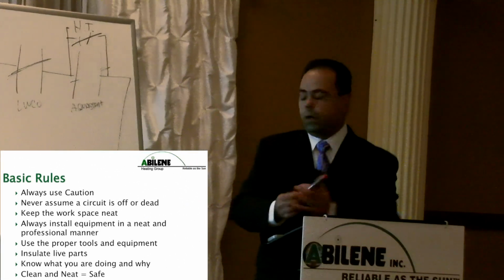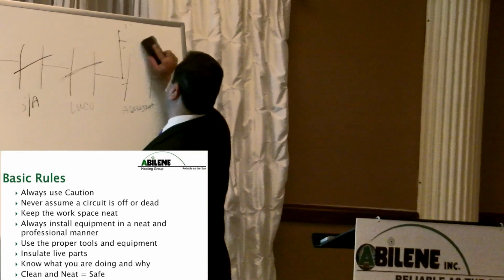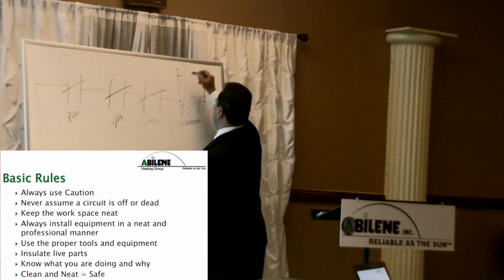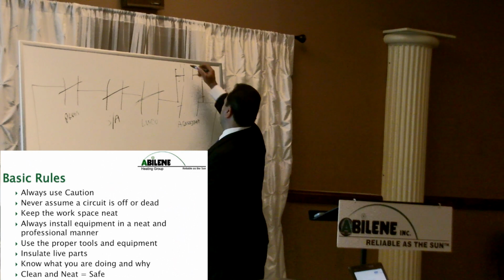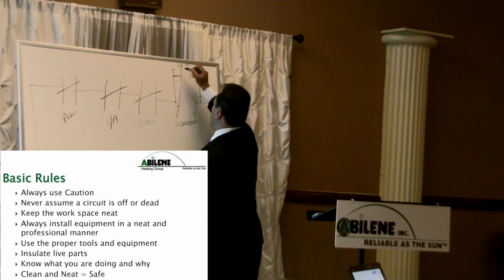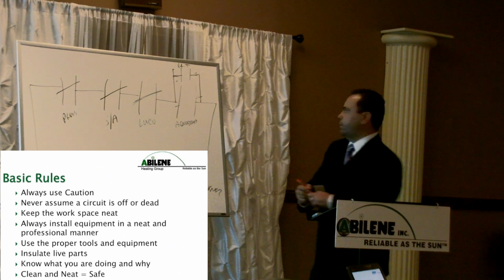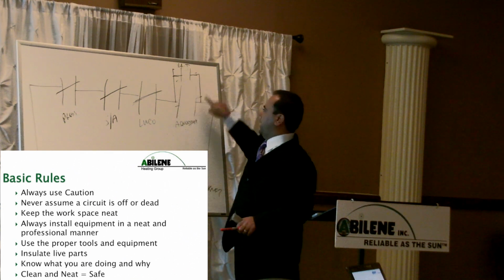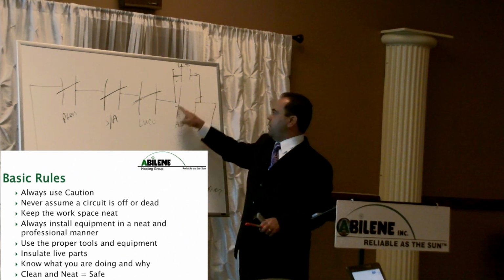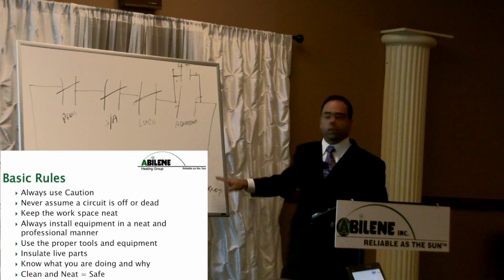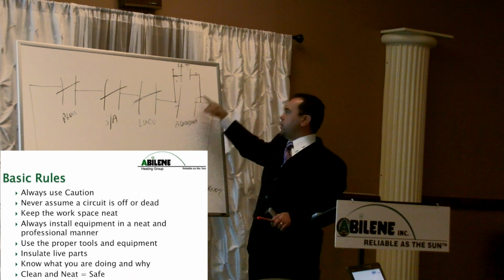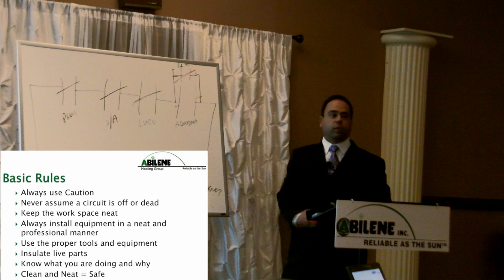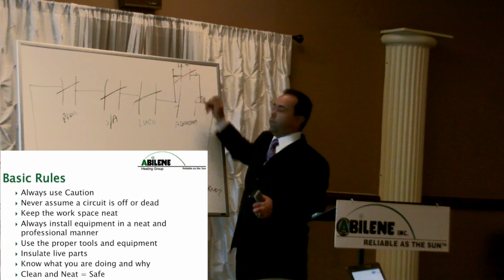Okay. I'm going to do this in red so you can see it a little better. Remember, we talked about switches, right? This is a switch. This is the heat timer. It's in parallel. Remember, we talked about parallel circuits, right? It's in parallel with the aquastat. So if the aquastat closes, it'll fire the burner, even though I don't need heat. If the aquastat is satisfied but I need heat, this closes and fires the burner. Either control can fire the burner.